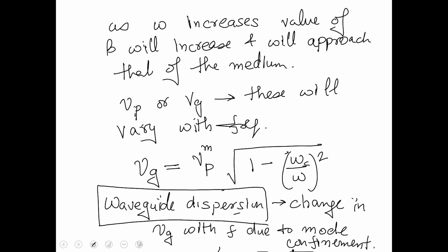And your Fourier tells you that when you have some time variation, if I'm turning this wave on and off, let's say I want to send ones and zeros, then because there is a variation in time, the signal would have multiple frequency components. And what would happen to these frequency components as they travel through the waveguide? They will travel at different speeds, and because they'll travel at different speeds, they'll start to disperse. So I would not get the exact same information back.